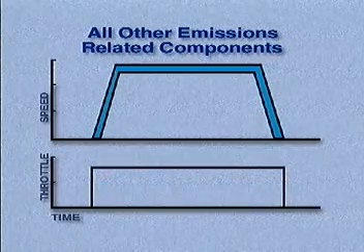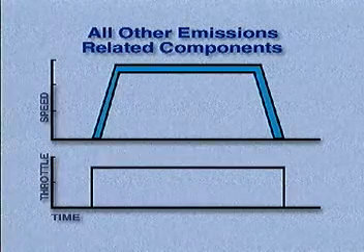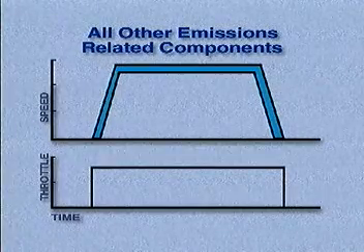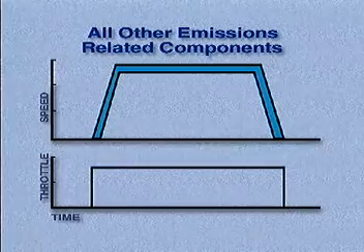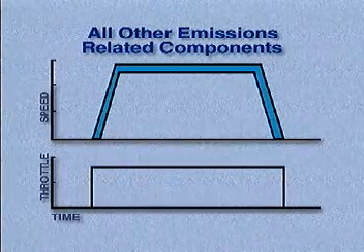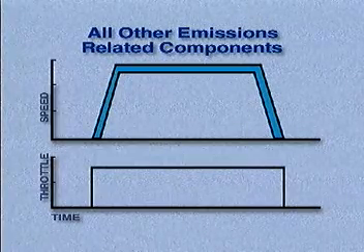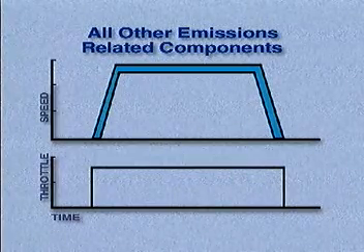Come to a complete stop and shift to park with an automatic transaxle or neutral with a manual transaxle. Allow the engine to idle for 5 minutes or more with the lights, coolant fan, and all accessories, including the air conditioning, off. Verify the completion of the readiness tests.